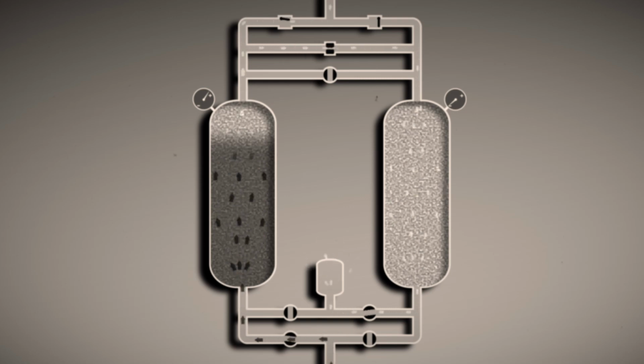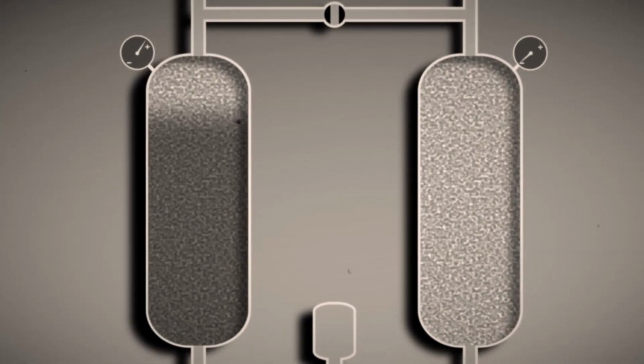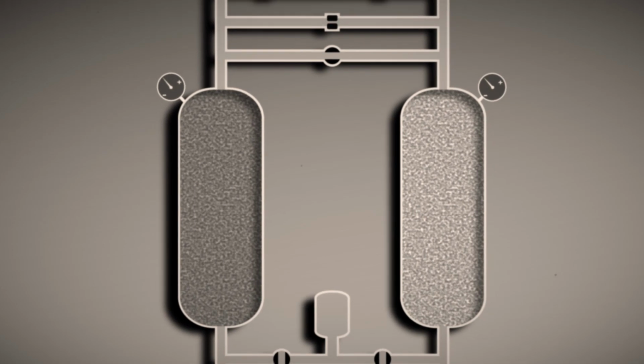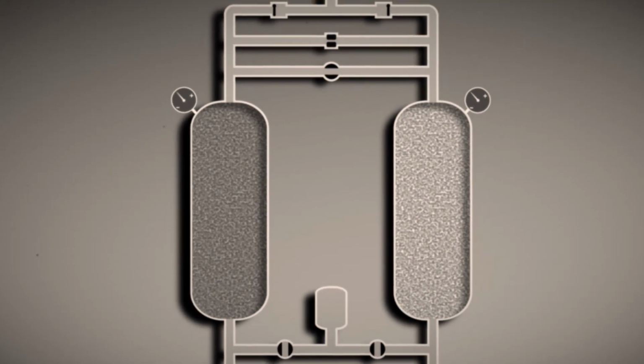We can instead use some of the compressed oxygen in the left sieve bed to begin pressurizing the right sieve bed. This is known as equalizing the sieve beds. The equalizing valve opens, joining both sieve beds together. Oxygen rushes from the left sieve bed to the right sieve bed until both of their pressures are roughly equal. Pre-pressurizing the empty sieve bed with oxygen helps jumpstart the nitrogen adsorption. Recall that zeolite adsorbs nitrogen better at high pressures.